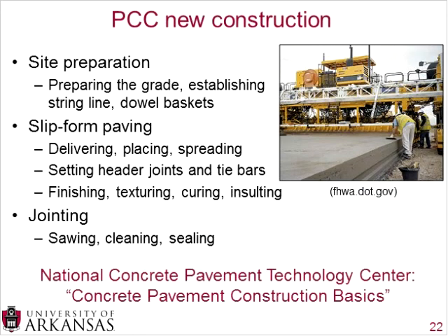We've talked a little bit about the basics of pavements, and a little bit about the mix design, and now we're going to talk briefly about the construction techniques of pavements. So when you're looking at PCC construction, you first need to start with the site preparation. You need to prepare the grade, which means you're building this pavement over some sort of native soil, or if it's a rebuild, you need to take into account what's underneath it.